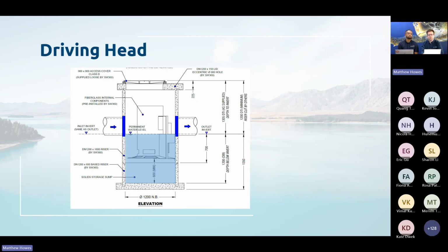With the cascade separator, we're achieving quite high removal percentages for coarse sediment, and broadly speaking, 50% TSS removal with a median particle size of 75 micron. So we're getting an awful lot of the sediment that even the storm filter would provide treatment for.